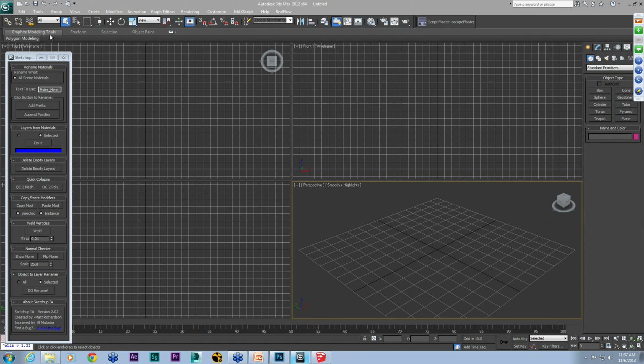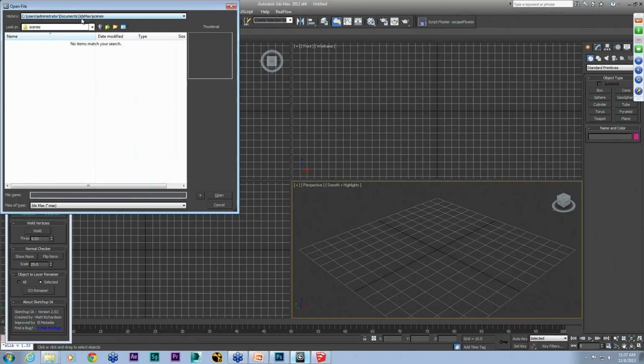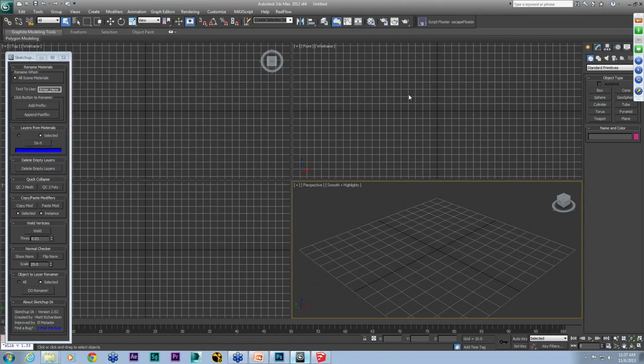Most architects tend to model glass as a single plane without any depth, and they're always glued to one another. Any different planes, they don't have any spaces between them. What do you do about that? So exporting, say, a SketchUp file, a lot of times the two-sided material thing is that way in SketchUp, where you're going to get a single plane in the front and a single plane behind it, two different materials. By exporting it the way I showed, you'd be able to separate out those two different materials and get rid of one.